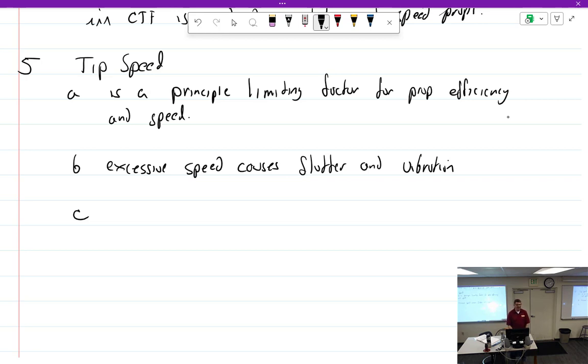That's not what I wanted to hear. He goes, yeah, the thing just didn't last. And had it overhauled, and it didn't last. Funny thing, Kevin, I didn't know that engine and propeller combination that I put together had a significant vibration area right in the middle of where he operated it nonstop. And it ate itself to pieces. And he went through like 3 engines before he figured it out.